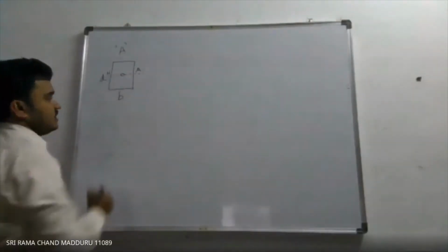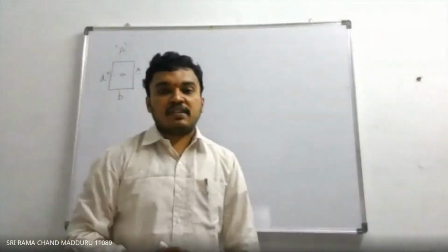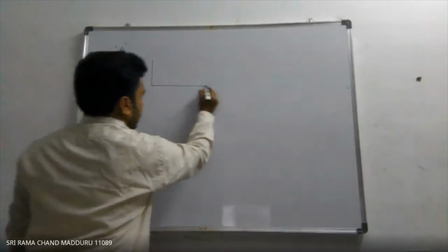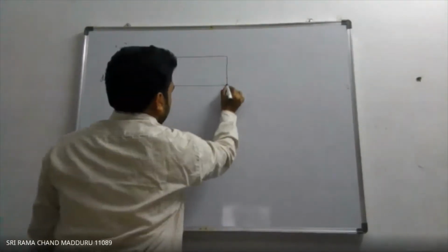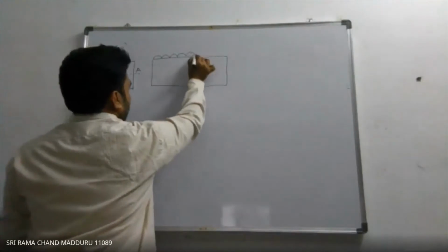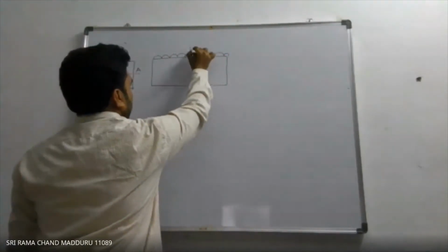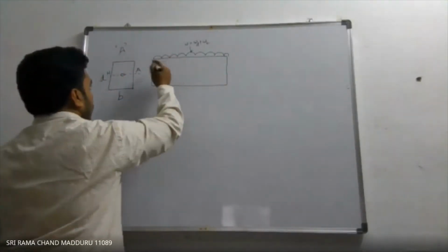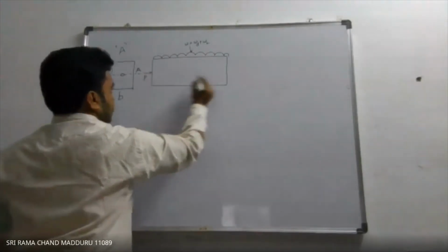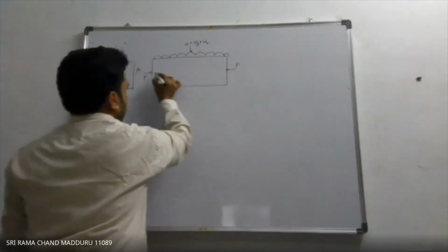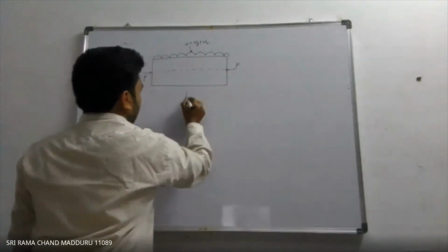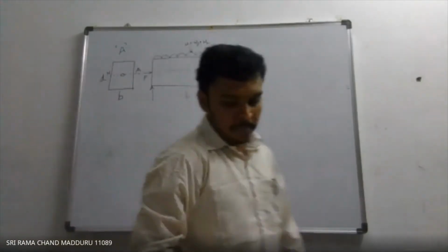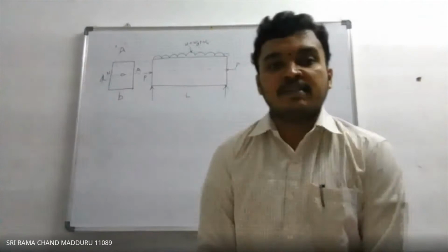Now here the pre-stressing is done at this point. So when the pre-stressing is done at this point, upon the span length L, and this beam is subjected to a loading W, and this W is nothing but summation of the load, dead load plus live load. And here the pre-stressing is done at the neutral axis with a force of capital P, and L is the span. I am considering it as a simply supported beam.